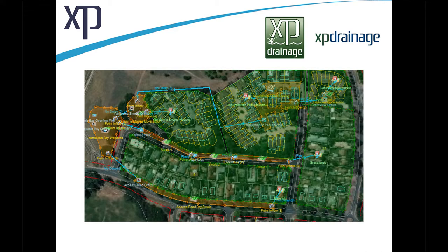So we're very excited today to show you our new software program, XP Drainage. We want to show you a workflow that can demonstrate in a quantifiable way an effective treatment train approach to flow and pollution control for stormwater management. XP Drainage can analyse water quality and quantity in stormwater designs that include a range of stormwater management devices, comparing pre and post development scenarios or phases.